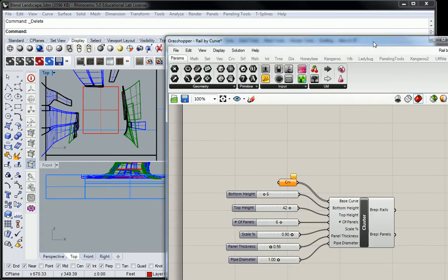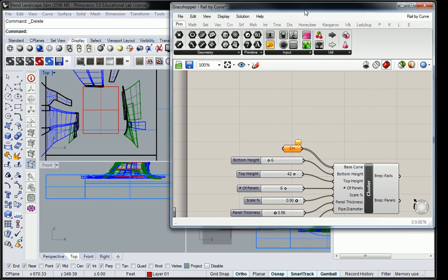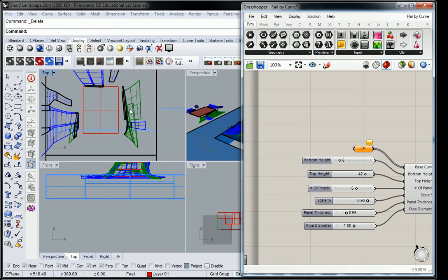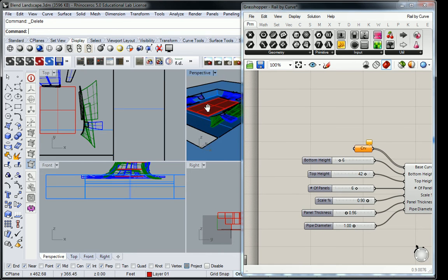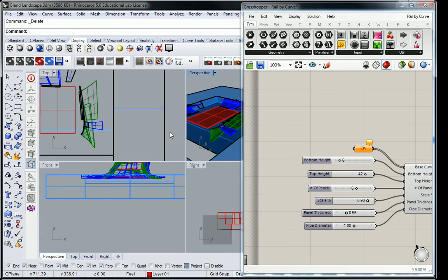So what we're going to be doing is using this very simple Grasshopper definition to apply guardrails, or basically just an edge or rail to the end of our surface, right? Well, you'll see. It's simple, and I think it provides a pretty cool level of elegance to a simple model when you're studying it in a schematic fashion. So we still have that surface at the top. I did mention not to delete it. If you did delete it, you can Control-Shift-click that top surface and make a copy.